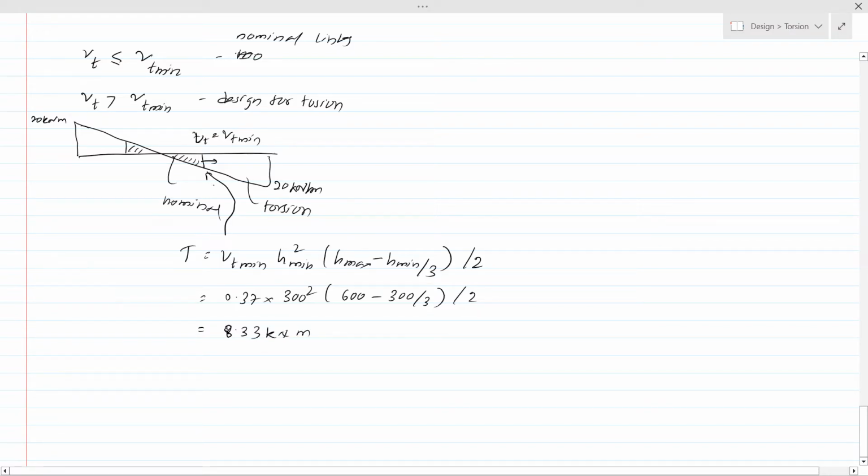Now we know the moment there, so we can also calculate the positions where we can avoid the links. I have considered one segment. We have calculated the moment at which we don't need to provide the shear links, and here we have 20 kilonewton meter. Since our span is 5 meter, this length will be 2.5 meter.